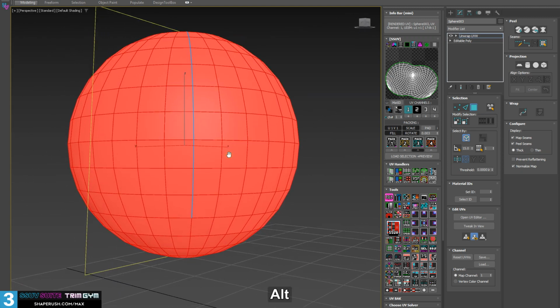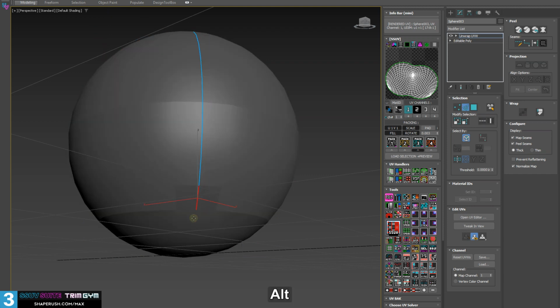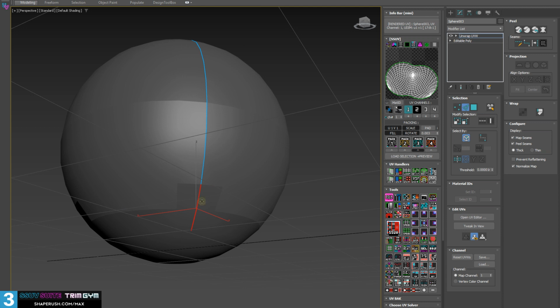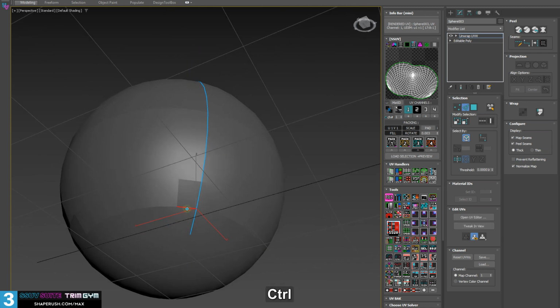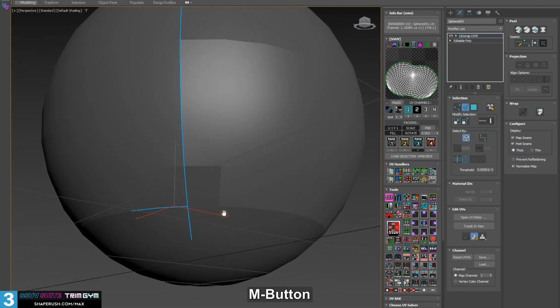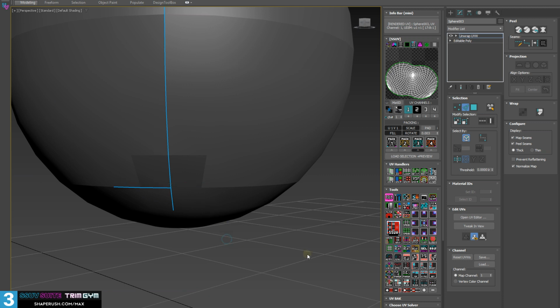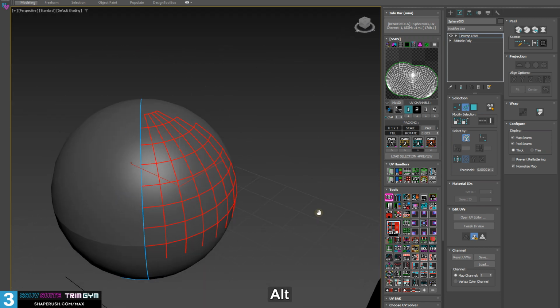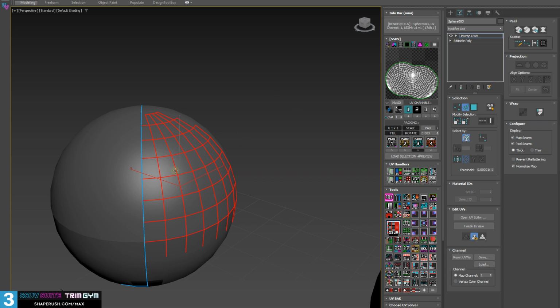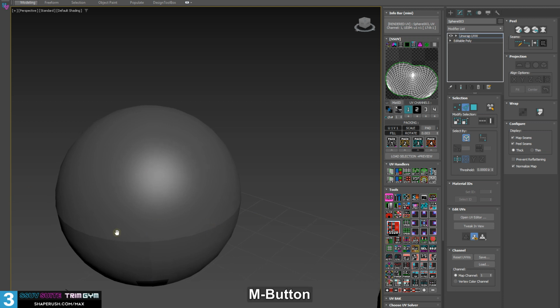Now, if I'd like to add or expand the seam, I can select more edges, and then left click. You see it will add those edges as seams. Okay. Now, if I want to remove all of the seams, which is usually what I do because I prefer not to work with pelt seams most of the time, I just deselect every edge. So you can see this by my example here. I have all of those edges selected, but if I just click and drag off of the object, no edges are selected. Okay. At this point, I can right click. That will remove all of the pelt seams instantly.